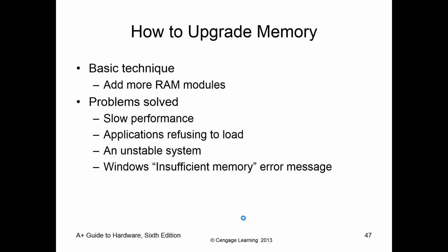It only goes in one way, and verify that you install it without forcing it in. Also, it's important to note, verify that the PC is turned off, unplugged, has no power, before you try doing any of this. I've had a few people that tried to install memory with the PC on, and it destroyed everything. So make sure the PC is completely off, unplugged, disassembled as much as you need to before you install the memory.